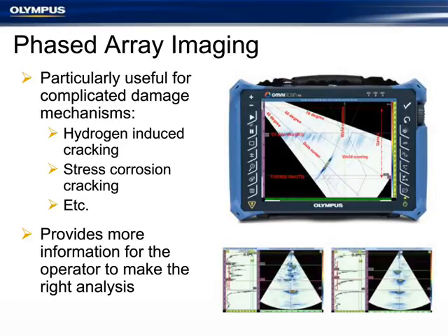Because just looking at an A scan, that can be a very tough thing to do. The bottom is another showcase of that. We actually have some phased array images from hydrogen-induced cracking. So this again, the conventional transducer, we might be able to say it's there, but having to do many long time of scanning to try to figure out what's the deepest branch, how serious is it, or do I just have laminations, or are there laminations connected where I have like a side step cracking that's connecting them, which is much more severe as far as for the pipe or whatever we're testing.